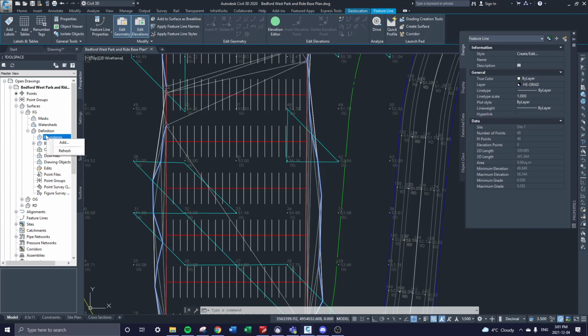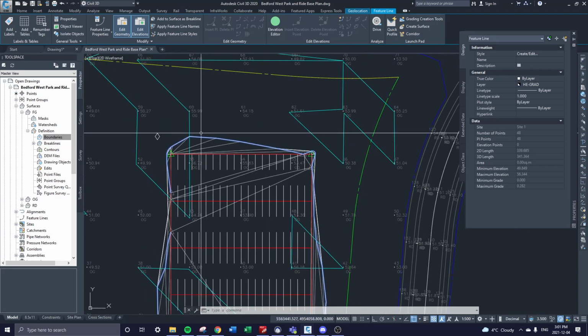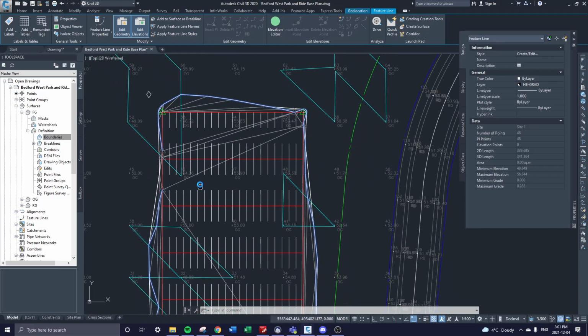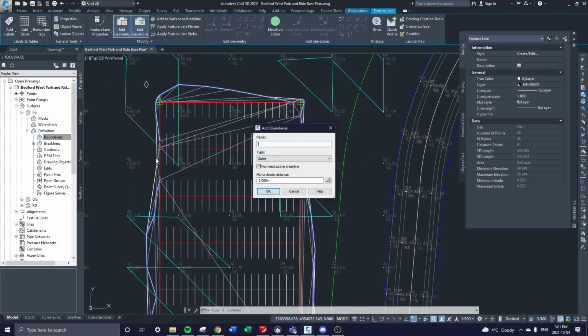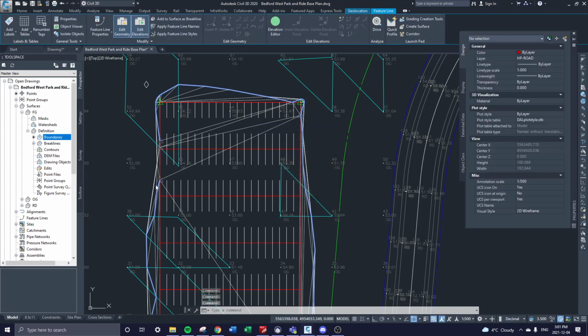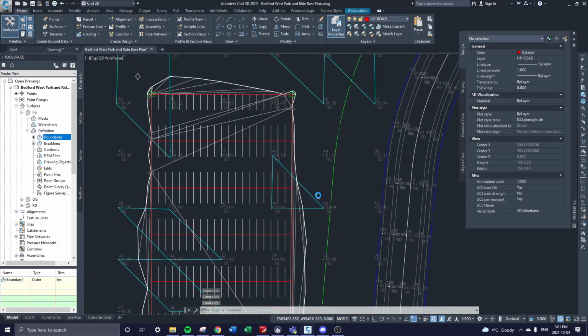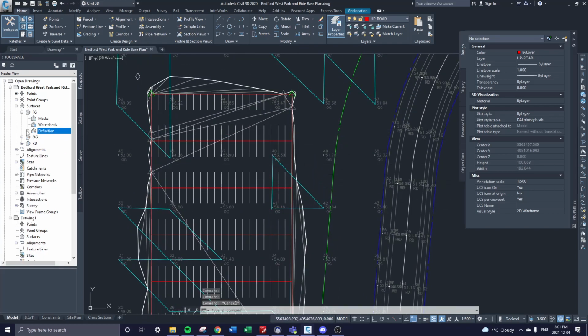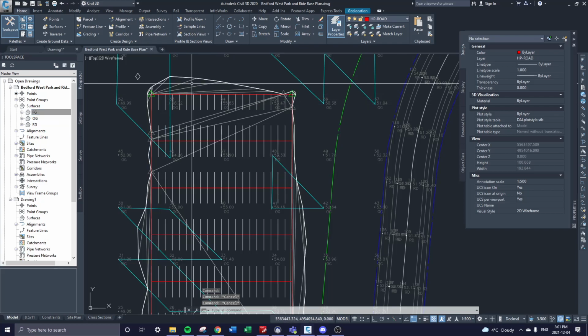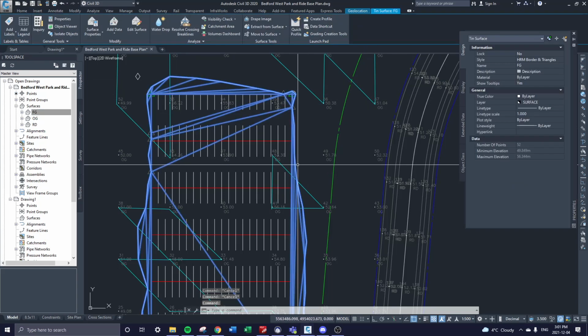So if you select your boundary, you have this panel open, you've selected the feature line that you've graded, and hit add, it's just going to trim the remainder. It's like trimming the fat off a piece of meat, and it'll make your results slightly more accurate. So let's take a look at this beautiful finish grade that we have.